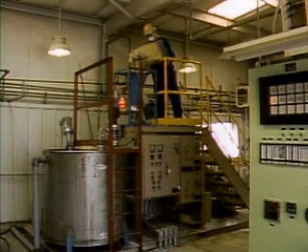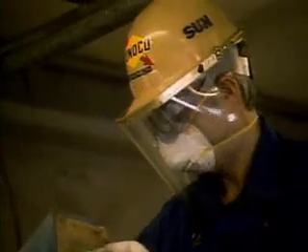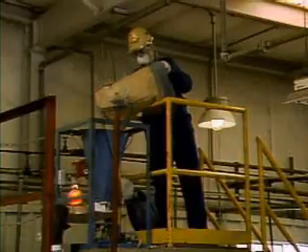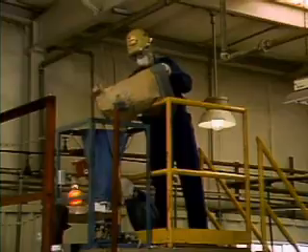Depending on the type of chemical that you work with, a face shield, rubber apron, gloves, and boots may be required to protect your body. In some situations, the chemicals being added may be in the form of a powder, so a dust mask or a respirator may be needed in addition to eye protection and other protective gear. Also, you should know the location of the nearest emergency shower and eye wash stations.